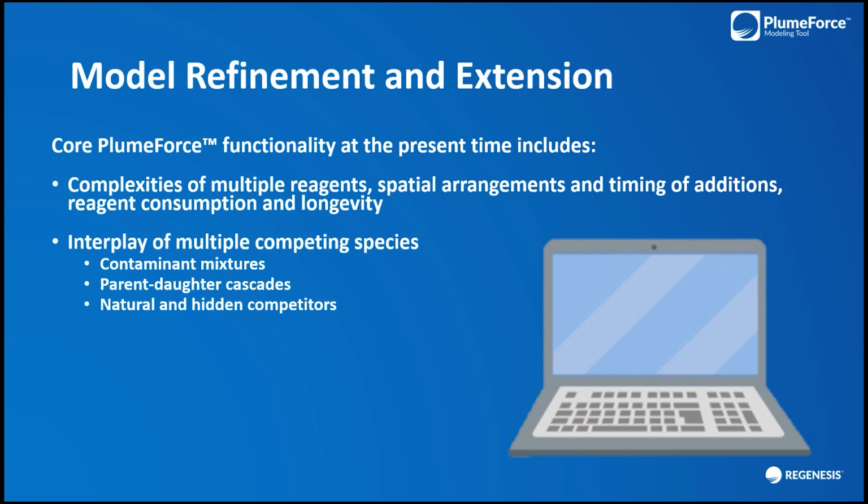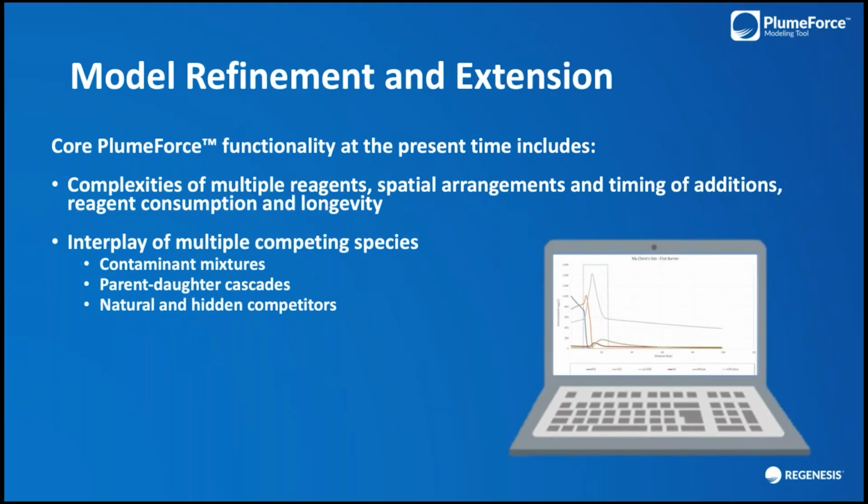It considers the interplay of multiple sorbing species. It handles contaminant mixtures and parent-daughter cascades. It considers natural and hidden competitors that might not be from contaminants of concern, or even in our analytical suite, but that will nevertheless compete with our target species for sorption sites on the PlumeForce activated carbon.